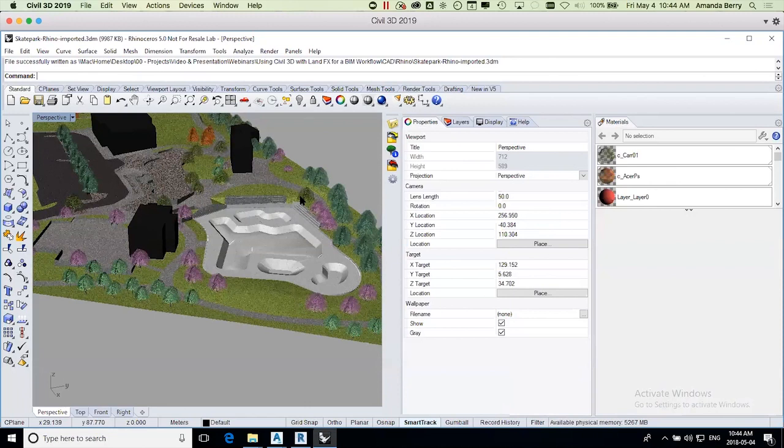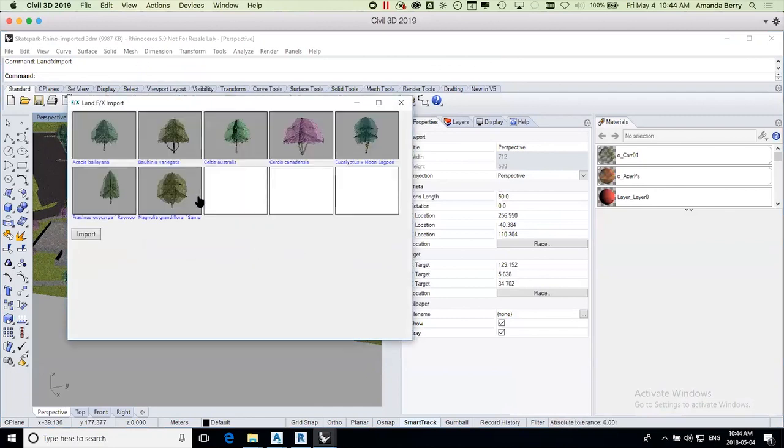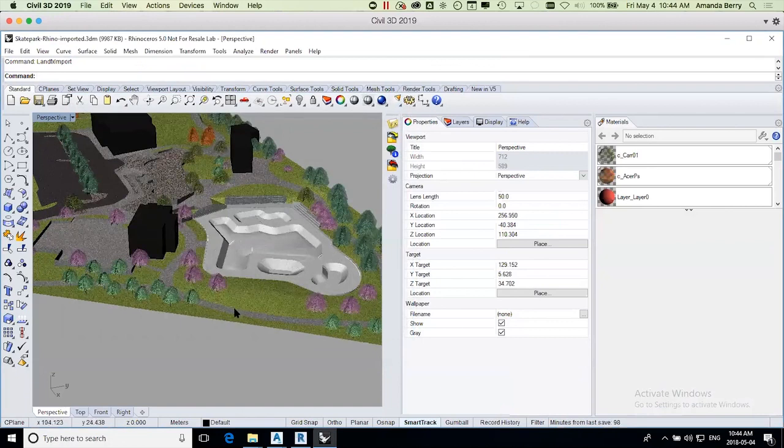Again, all I did was import it, assigned different components and just went for it. Imported it, it all came in at the right scale with the right component, and you can always assign your own higher graphic components as well. So it's the ability to kind of go back and forth. And I could actually move things around here in Rhino and even export that back out and then import it into SketchUp, and it will go directly from there. So now we have a three software capability.